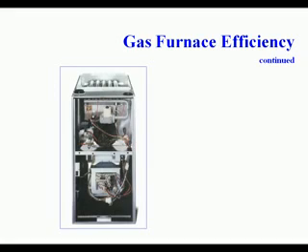High efficiency furnaces may contain improvements in flue pipe routings and high heat transfer exchangers. Secondary heat exchangers that extract as much heat as possible from the system also may be present. The temperature at which the flue gas is emitted to the atmosphere is greatly reduced. Reduction in the flue gas temperatures results in condensation of water vapor in the flues. This is an example of a high efficiency furnace. PVC flue piping is used for flue exhaust and air intake.